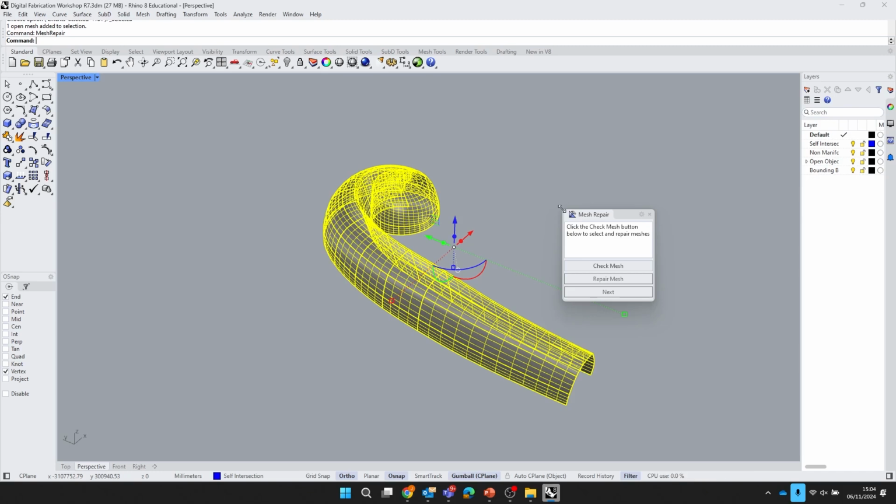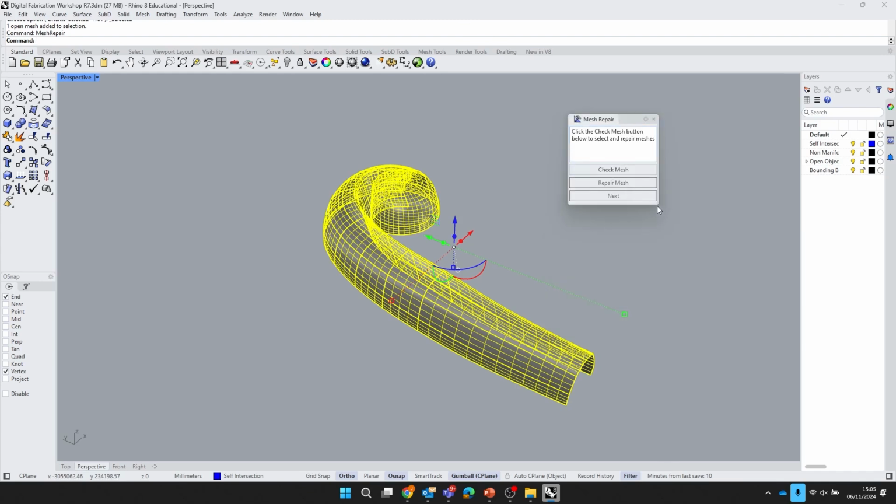If you're importing your SketchUp models, obviously they come in as mesh objects, just like this. If you want to convert those to Rhino objects, you can do that, and I will be covering that as part of this whole process we do today. But the most common issue you'll ever find with a SketchUp model is self-intersections. See it all the time. And non-manifold edges.